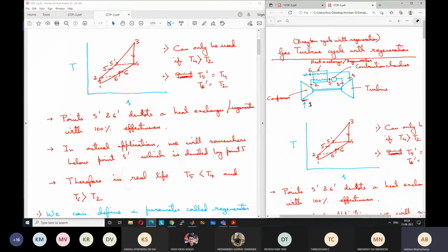Your turbocharging process is a very different process. A turbocharger's role is not to increase the temperature. Here, the role itself is to increase the temperature. A turbocharger is there to increase the amount of intake air. Without any supercharger or turbocharger, there is a certain amount of intake air. A turbocharger or supercharger compresses the air and increases the amount of intake air, which is much more beneficial. That is the actual role there. It is incidental that the temperature increases there, but here the role is to increase the temperature in a regenerator.